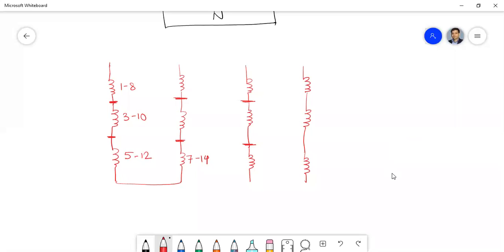What is the next coil? Are you there? You are not responding. 9/16. Okay, so it's 9/16, isn't it? Next, 11/18. Now 11/18 again will be connected with which coil? 13/20. Then 15/22. Then 17/24.